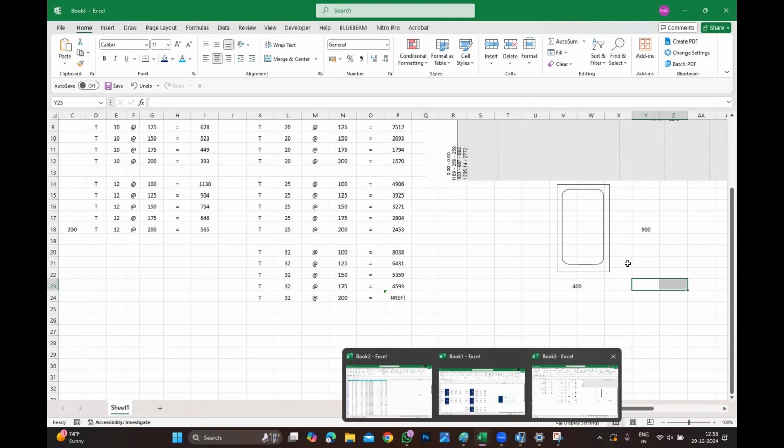As per code, the bar to bar spacing is required only two times the aggregate size, the minimum spacing. But that does not work actually. Now it is contradicting. If you're using chips, if you're using 20, then it becomes 40, and you cannot use the same vibrator.